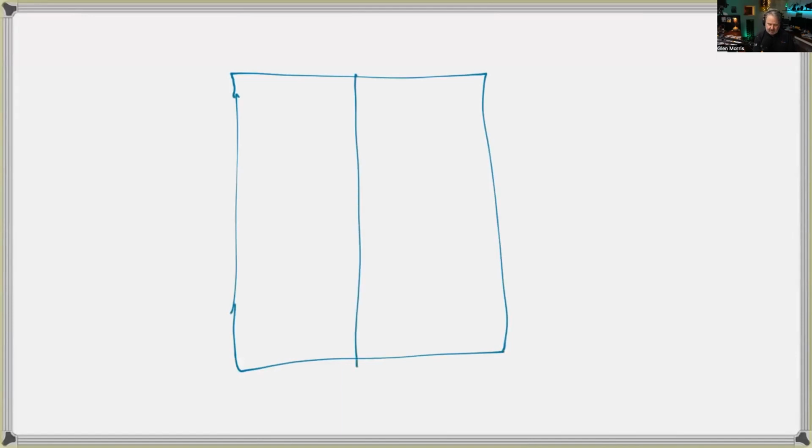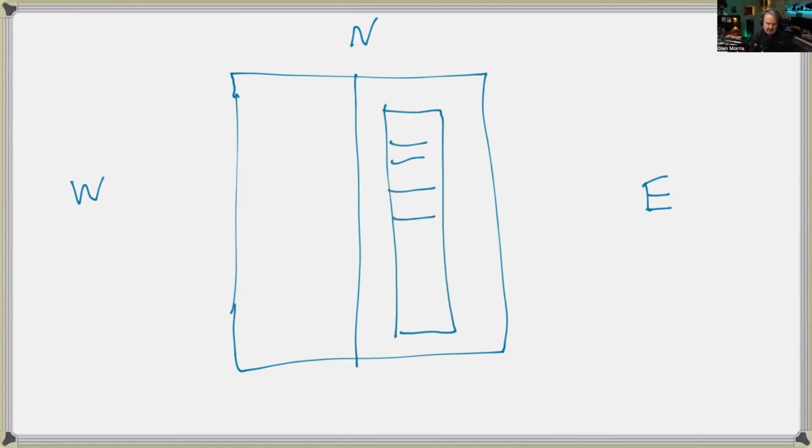And let's say it's my favorite type of house, which is just two big plain surfaces, no hip roofs, no dormers. And there's north, there's east, there's west. Now, if you look at solar radiation tables, it will tell you that you'll get the most energy on a north-facing array, and there'll be an optimum tilt angle, and that'll vary with latitude. But if your house is not facing north, it doesn't actually work in an economic sense to try and tilt all the panels to north. You would be better off putting them on the two surface areas that you already have, parallel to the roof, like this.